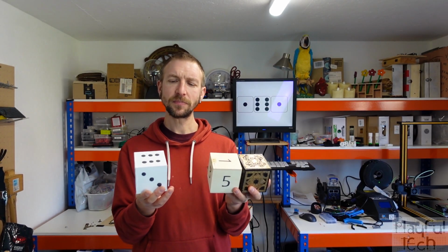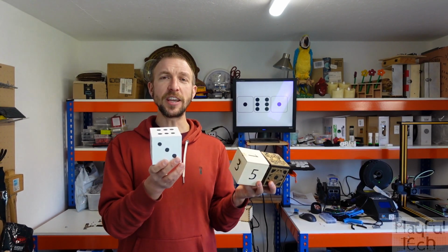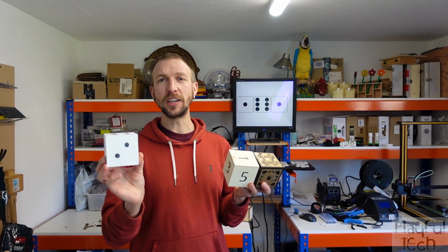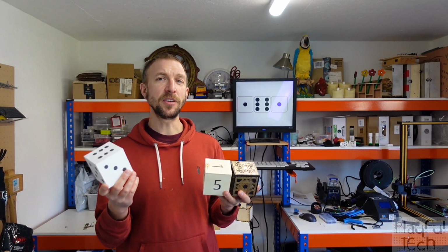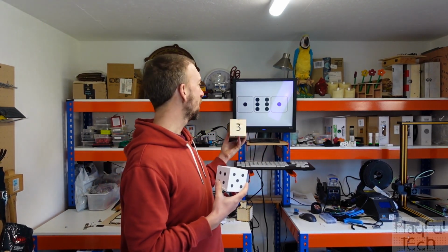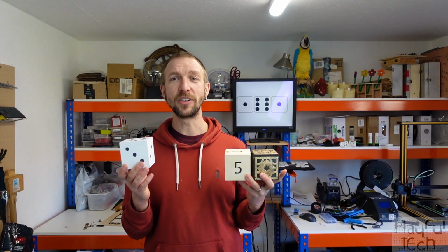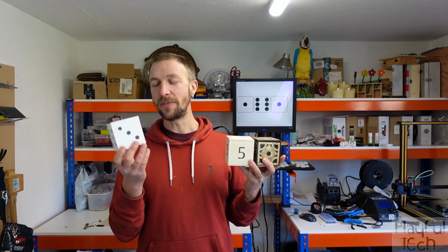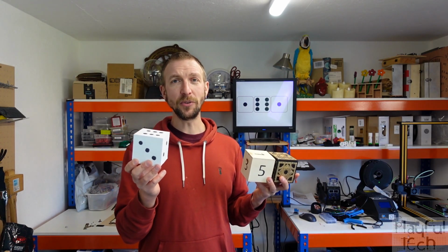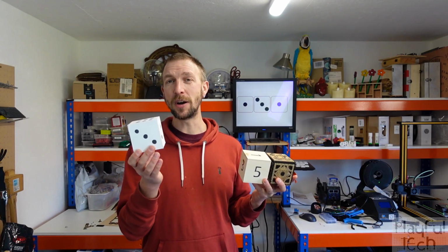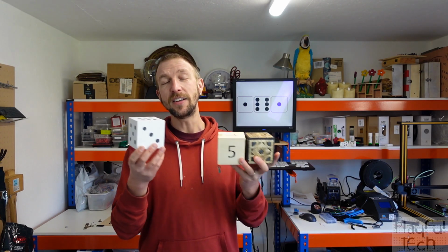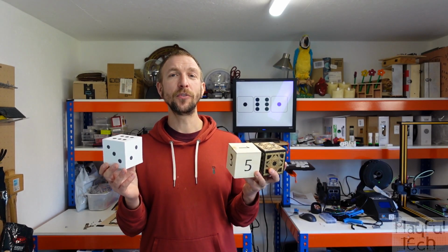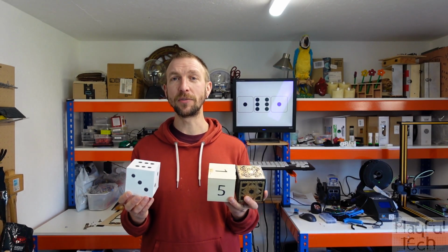landscape mode. And what happens is the ESP polls the sensor, it works out which way the cube is pointing, and then it sends that as an MQTT message to a Node-RED instance that's running on the computer behind me, and that's what updates the display. They're very cheap and pretty straightforward to build. They only cost about $5 each in components for each one of these. And in the rest of this video, I will show you all of the hardware and the software you'll need to be able to make one yourself.